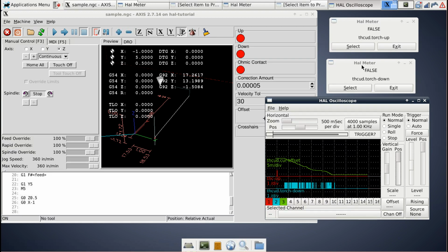When debugging a PCB, you usually use an oscilloscope. When it comes to HAL, you use the halscope. It's another tool I'm pretty sure I haven't shown yet, but I did want to cover it at least briefly because it's a very useful tool to have. Just like an oscilloscope, you've got channels, you hook up probes, those watch signals. But following the same parallels as before, these probes are software probes going to HAL signals.